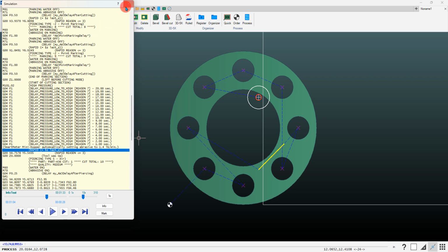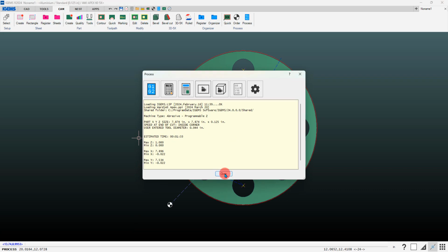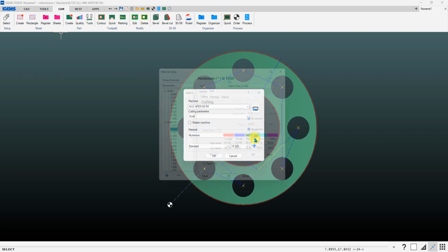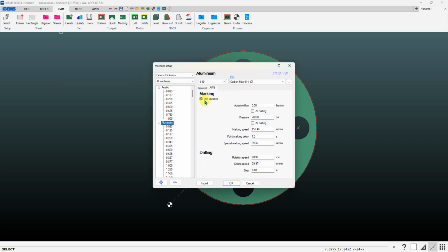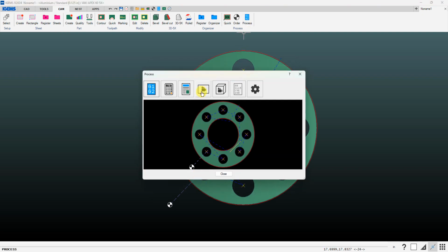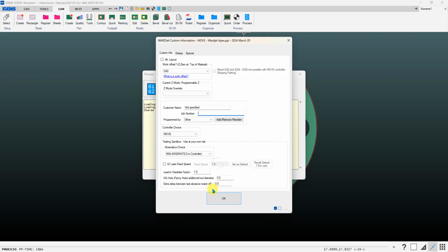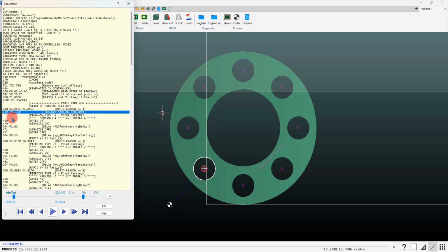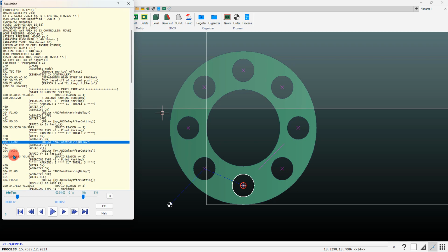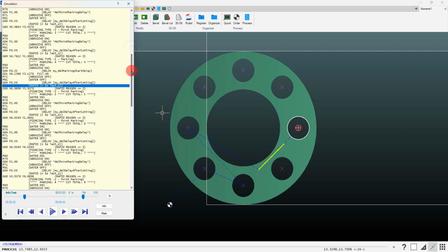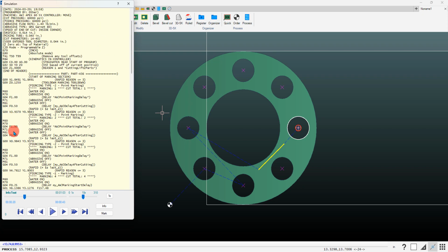Now if we just want to mark those at full pressure with full abrasive amounts, we would just go back into our material, again top level, and then we check these boxes, and then everything will be done at high pressure. Still have the 1 second delay, 1 second delay, quarter second delay on the line, etc., but no changes in pressure or abrasive.